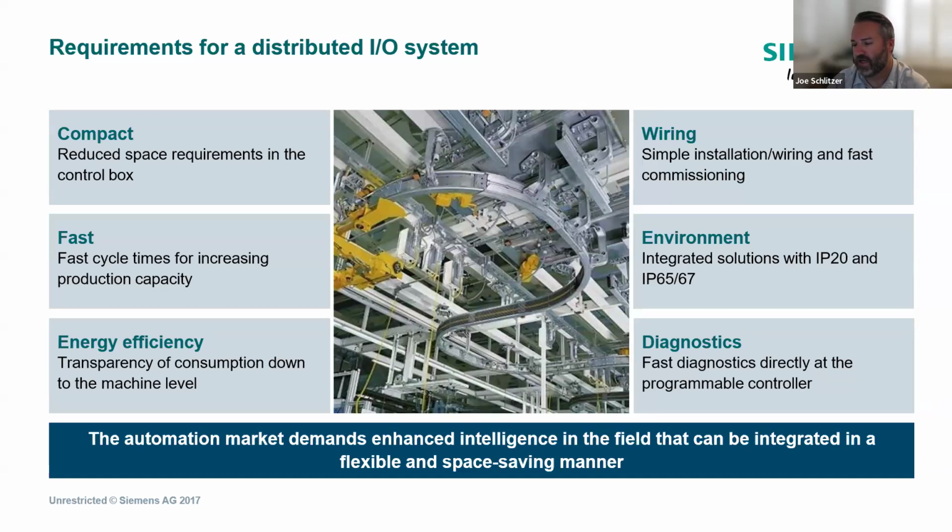The ET200SP base units are all push-in connectors, so you don't have to mess around with a screwdriver getting your wires plugged into the terminals. There are different versions of it. The ET200SP is IP20, but there are different flavors of the ET200. So if you need something that's going to be mounted outside the cabinet, there are flavors for that as well. And then like all of our other PLCs, there are many different levels of diagnostics that you could get back to your CPU for troubleshooting purposes.